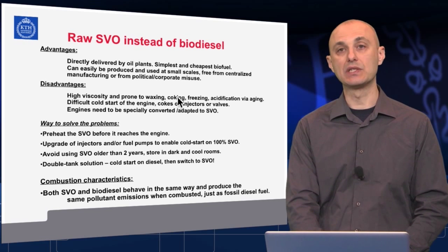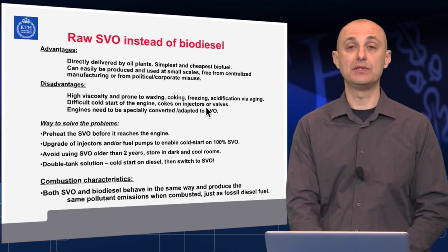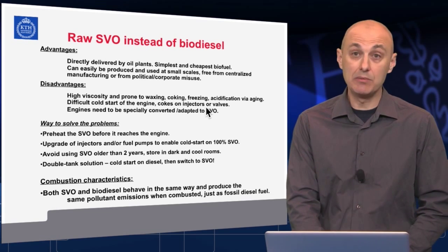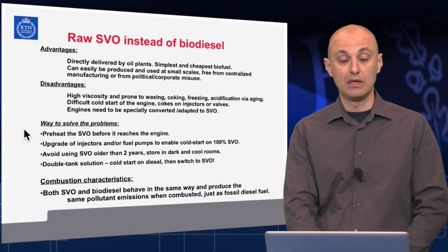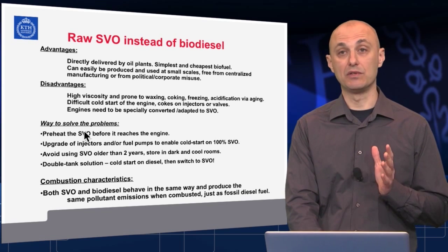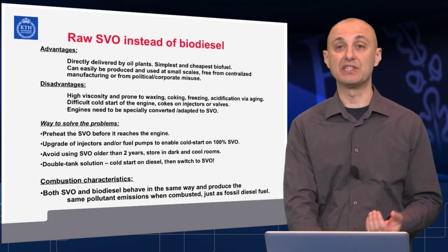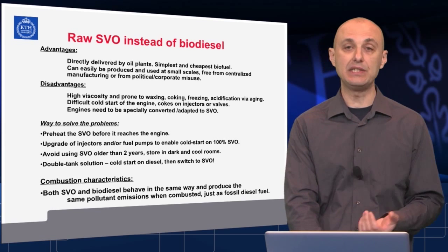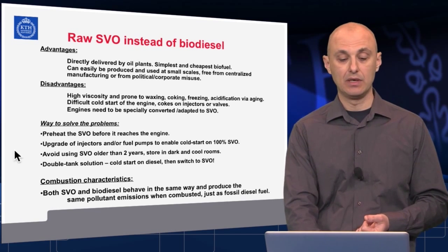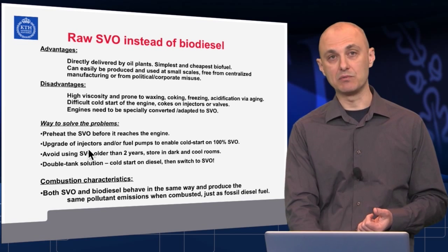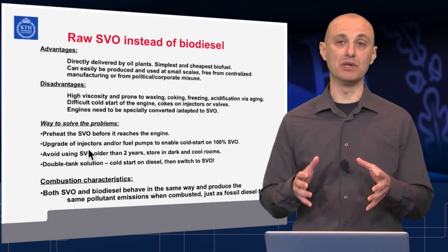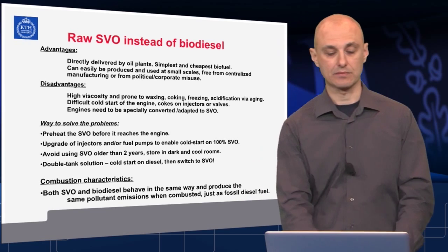If we would be using straight oil in a diesel engine, and it's definitely possible, I have been doing that for 15 years, we have to preheat, first of all, the fuel itself before it reaches the engine. It is much more viscous. It can also freeze at low temperatures. Upgrade of injectors might be possible, so adapting the engine to the fuel might be necessary.